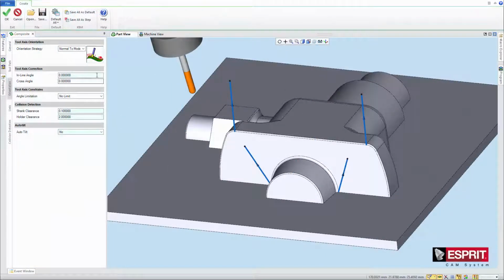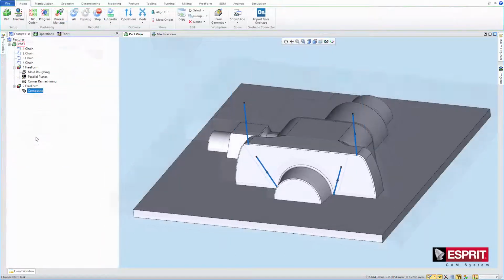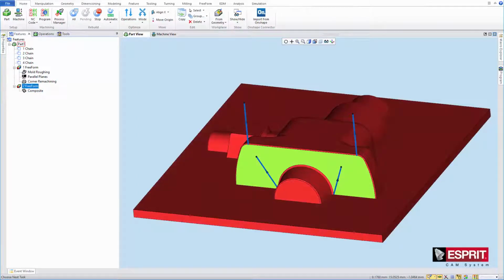This first example illustrates the vector field option. This option is available in cases of parametric parallel planes intersection with spine curve, and contour offset patterns. The vector domain is the 3D space around the model. A composite milling process has been applied to a freeform feature. This wall face is defined as the part, and the rest of the model is defined as the check.